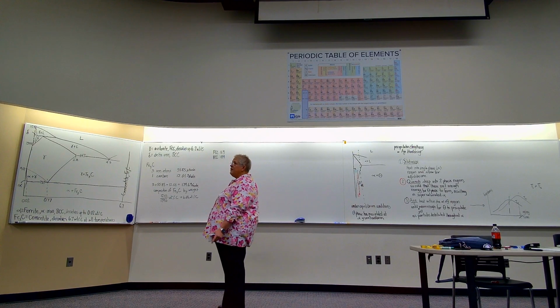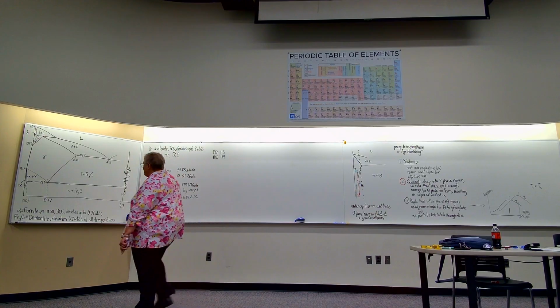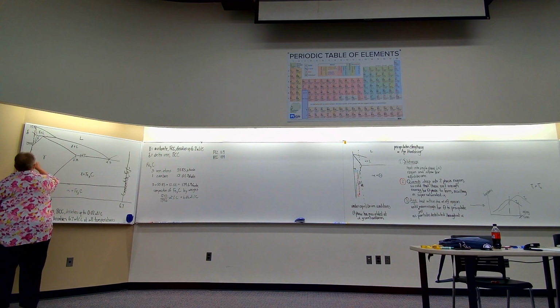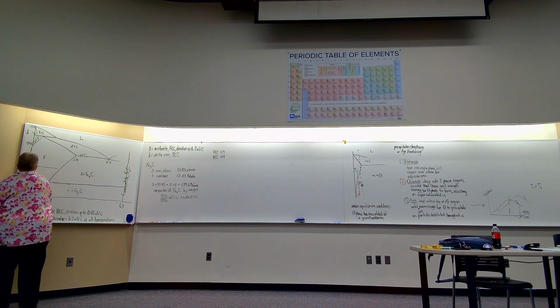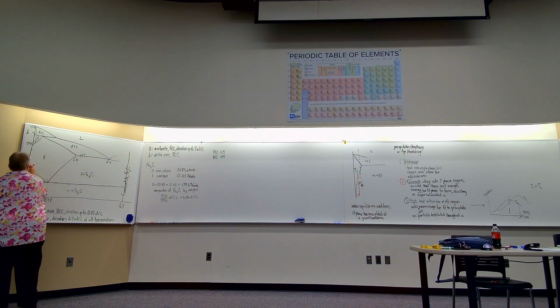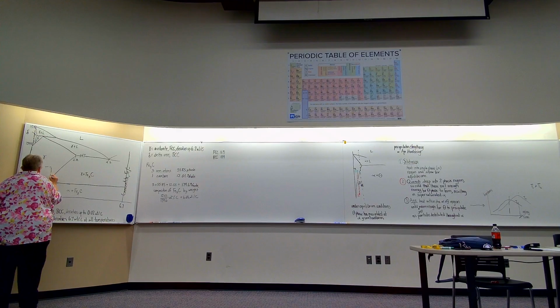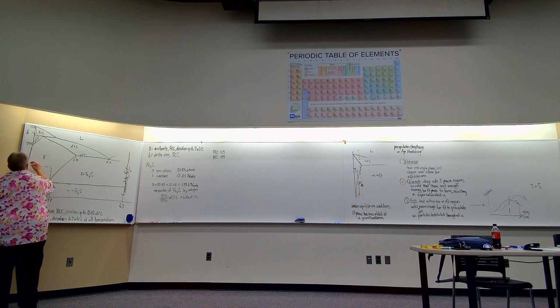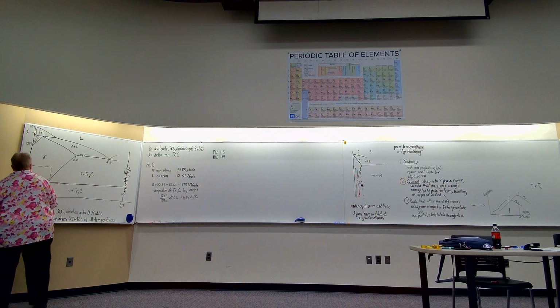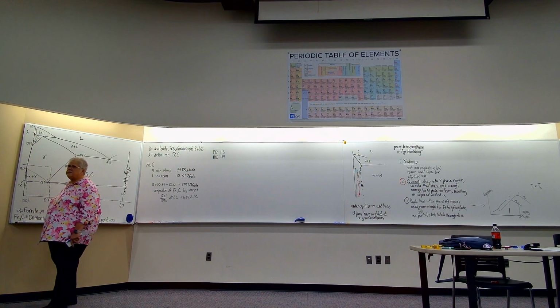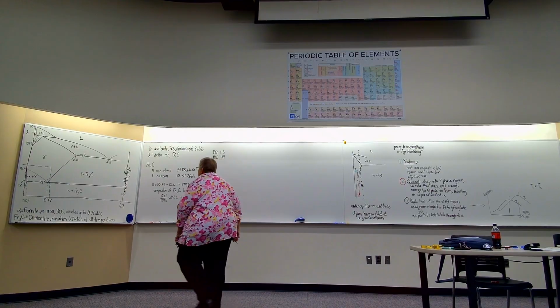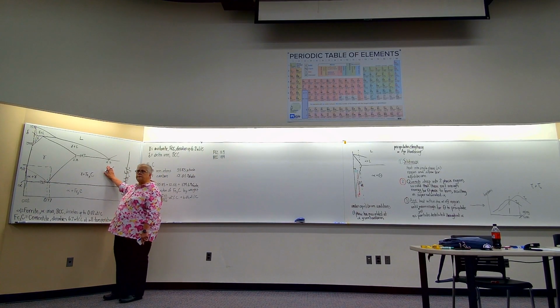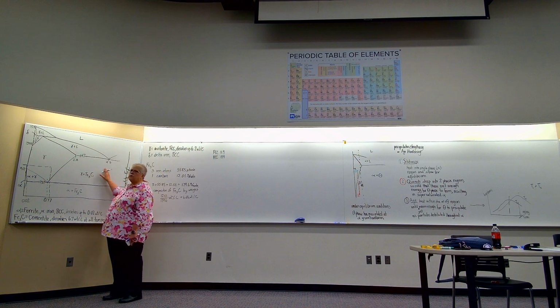All right, now, given that whole big phase diagram, the part of this phase diagram that metallurgists in steel deal with is actually just that. The rest, we don't even care about. We're only going to be looking at just that piece of it for heat treatment. 4.3 weight % carbon, that's cast iron. So over here, we're talking about so much carbon, it's not an engineering material.